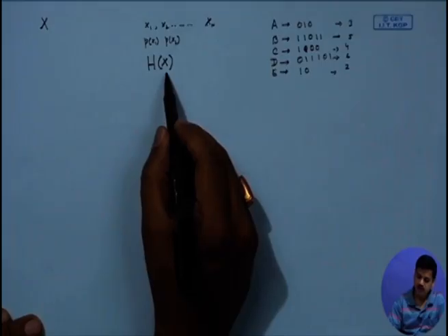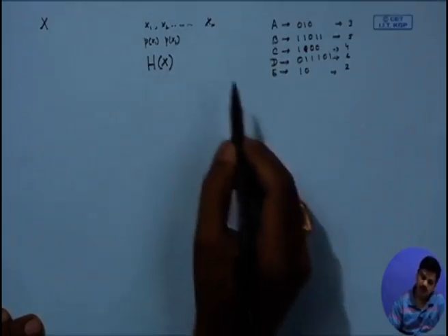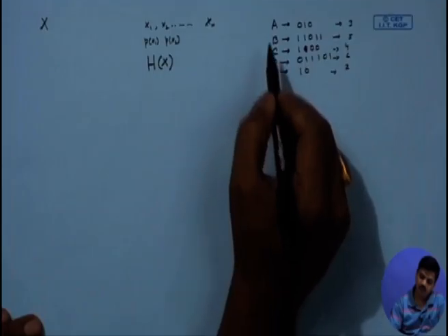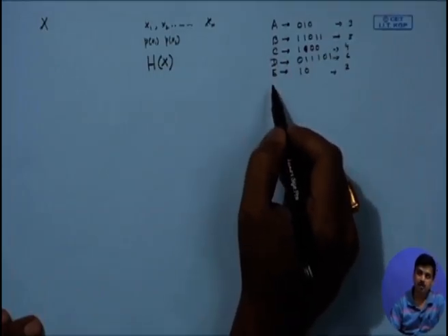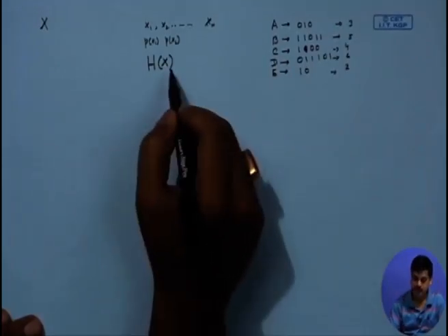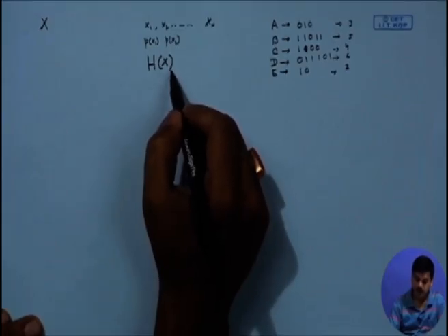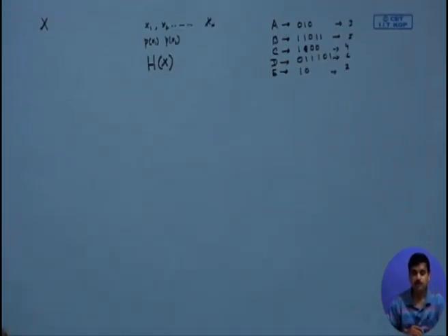What H(X) is going to give us is the minimum value of the average number of bits per such symbol that could be used. So, that is the measure of entropy, and we all know what it is important for. One direct example would be that it gives us information about the maximum amount of compression that could be done on the output of the source. That is one way of using it, and of course, we are not going to use it in that sense here. We are just going to look at entropy, because it is so fundamental that it will be used throughout until we arrive at the expression of capacity finally.